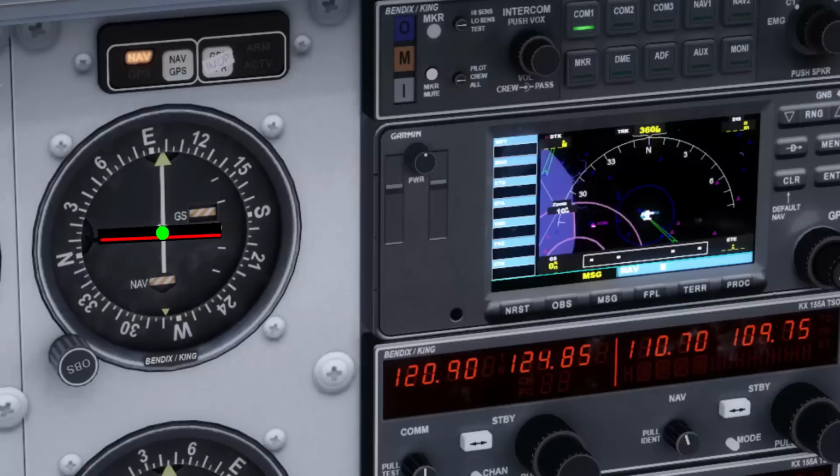Lighter general aviation airplanes are sometimes flown a little above the glide slope. Otherwise they need to fly a power-on approach, with more power for the same airspeed. And in case of an engine failure, you are better at a higher altitude.